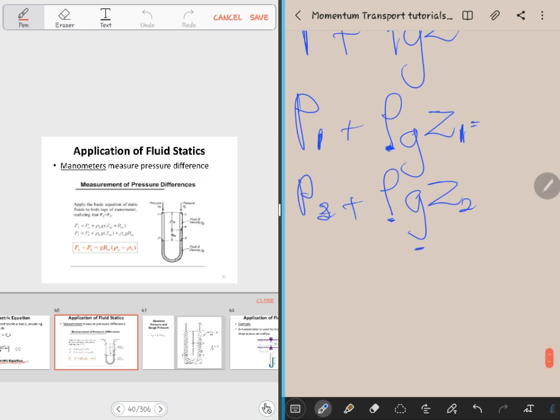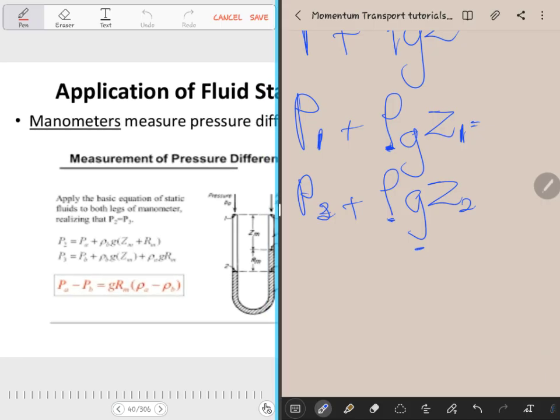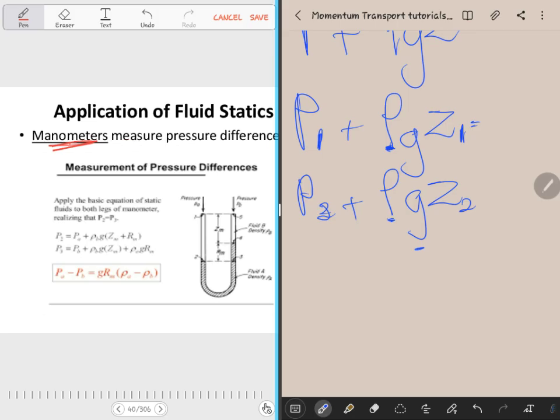That's what it's saying. And then when you rearrange this whole thing, let me magnify this, if you want to find the pressure difference, because manometers are used to measure pressure difference, right? And then we derive the barometric equation from the hydrostatic equation. So if you are measuring the pressure difference, we just have to rearrange this. We know this density is the same. So if I choose, it doesn't matter, irrespective of where you put it, it should be the same.